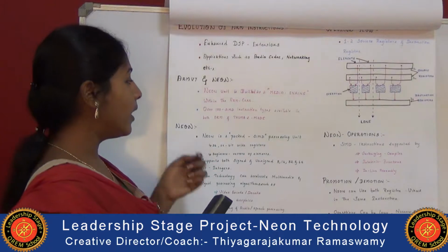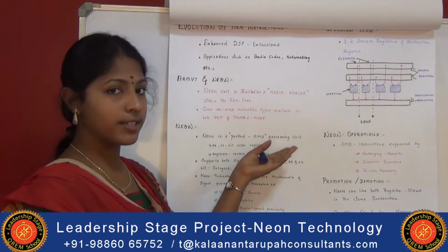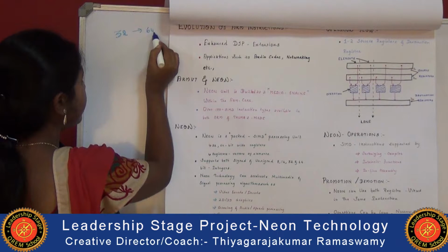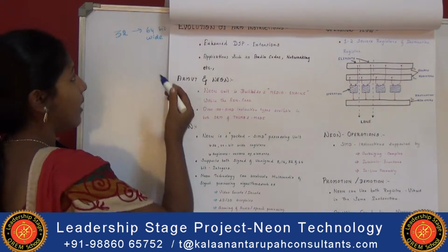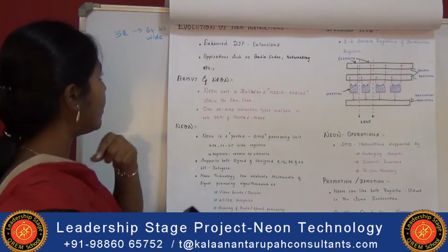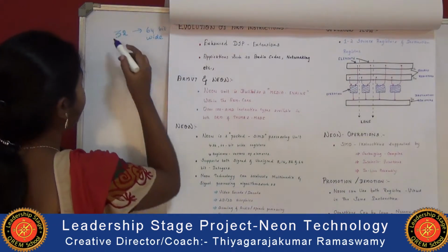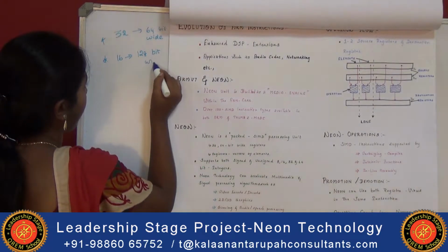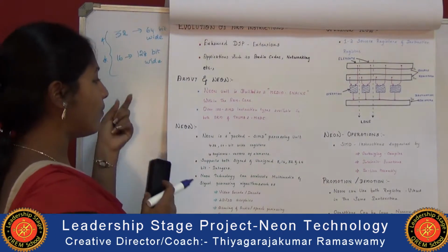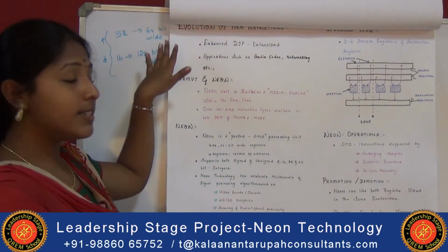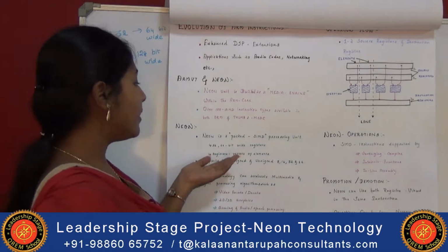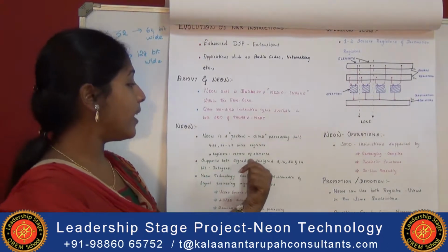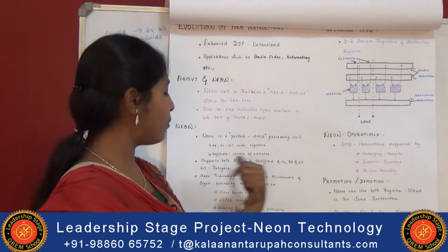Particularly, Neon is the packed SIMD processing unit, that is, a single instruction multiple data processing unit, and it has 32 registers that are 64 bits wide, which can also be viewed in a dual view as 16 registers that are 128 bits wide. The registers are considered as vectors of elements, and it supports signed and unsigned 8, 16, 32 and 64-bit integers.